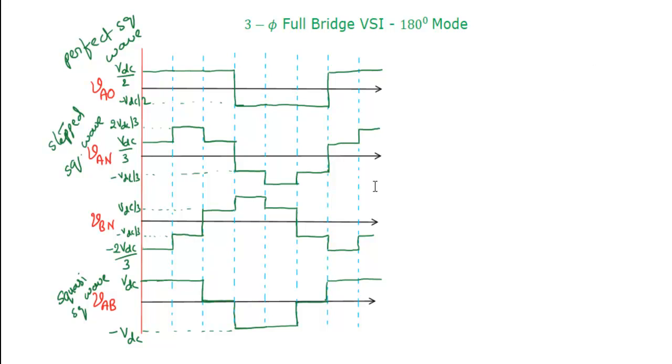Okay, so we need to discuss here the output voltage waveform, output voltage equations. Which one is easy to calculate the RMS voltage? Line voltage is easy or phase voltage is easy? By looking at here, if you take the phase voltage, we can calculate the RMS value by using phasor. But you can see that here in line voltage, if you consider half of the waveform, you have 2 segments. One is a square, the other one is 0. So it is easy to calculate.